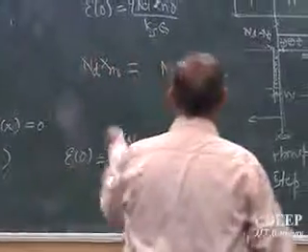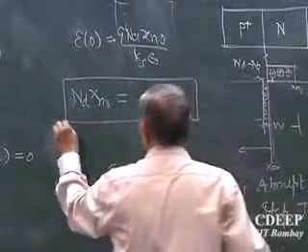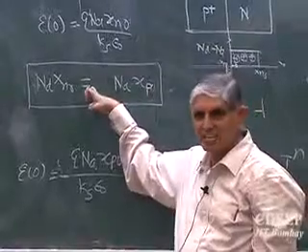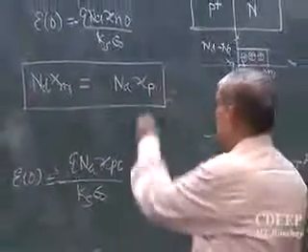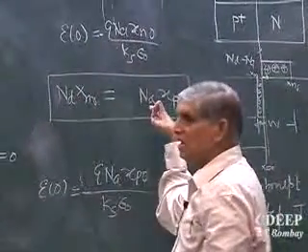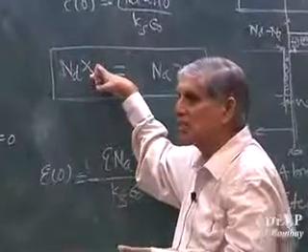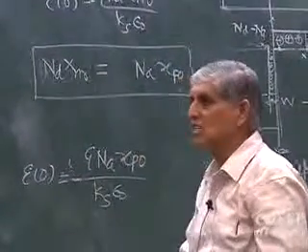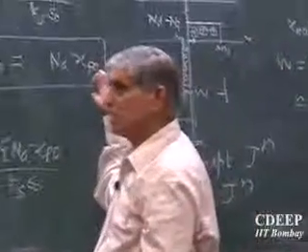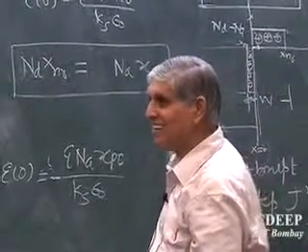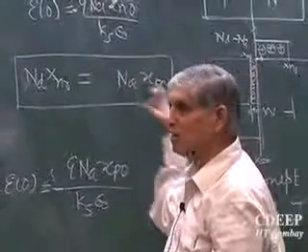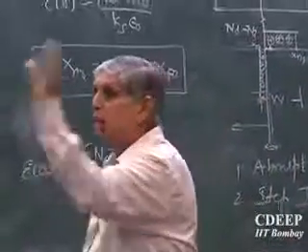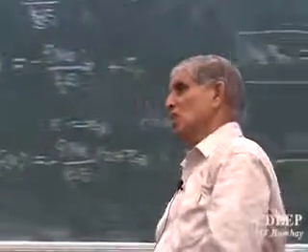Now this is the thing which we did earlier in the abrupt junction. Now look at the value. If Na is much larger than Nd, as in the case shown here, xpo will be the ratio of Nd by Na times xno. Nd is much smaller than this, so xpo will be very, very small compared to xno, or vice versa if it is an n plus p junction. So please never make xpo 0, because then this equality will not hold, it will become an inequality. So xpo always exists, but this relation is always valid. Nd xno must be equal to Na xpo.